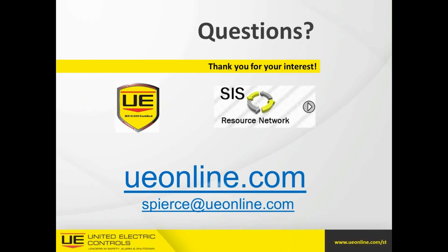And the way we do it is very unique. We have an analog output, which is a 4 to 20 milliamp output, and it saturates low if there's any fault with the device. We also have a local indication for health and the process variable, but we added a diagnostic digital output to the device. In most devices, the 4 to 20 milliamp output does not have the ability to check itself for accuracy. But with the safety transmitter and the internal checksums that we have, we're able to watch that 4 to 20 and compare it to the published accuracy. If it were to drift off or change, the digital output will indicate in an open state that there is a problem with either the device or that 4 to 20 milliamp output.